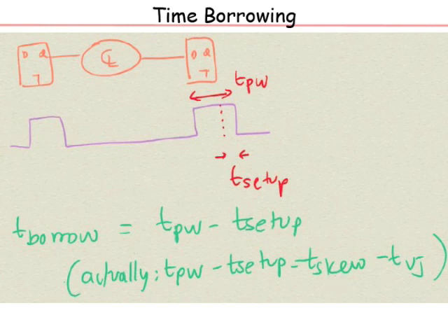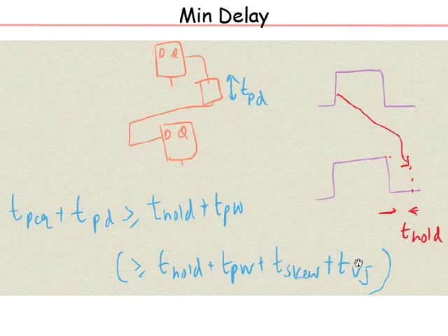Is it like the data should be maintained constant? Yes. The clock edge is happening. All the hold time is saying is, with respect to the clock edge, how much time should the data be kept stable? Remember, hold time can be negative also, as we discussed in the last class. But here I am just showing it to be a positive number. So, data should be